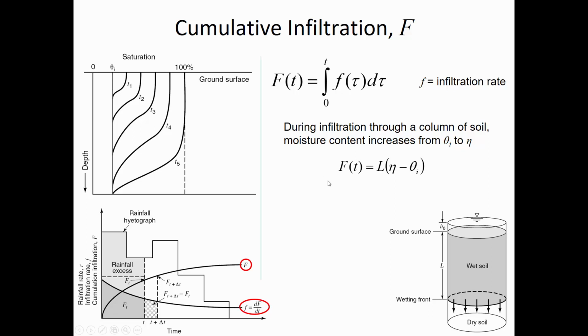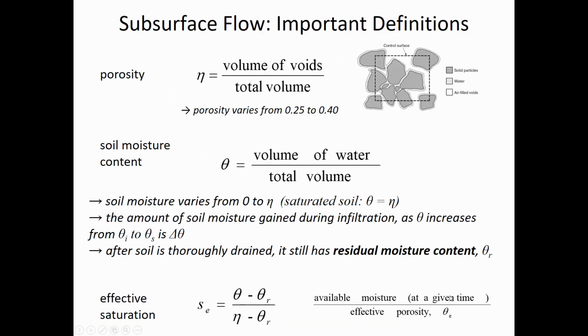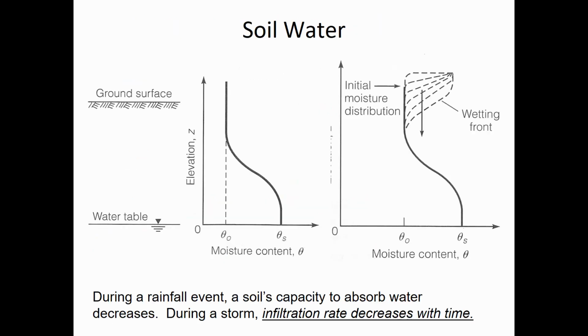But I just wanted to point out that the penetration depth is not the same thing as how much was actually infiltrated. Just because it's a matrix, if we go back to that figure, to begin with, there are solids and some initial water. So the volume that's filled with air initially is the only place that the incoming water can go. And so if we have 1 unit of water, it's going to infiltrate much deeper than 1 unit of depth.